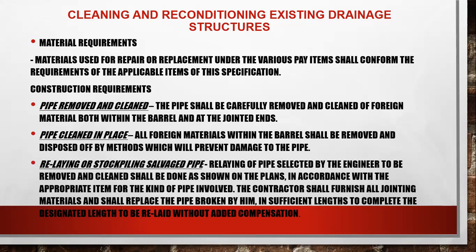Next is relaying of stockpiled salvaged pipe. Relaying of the pipe selected by the engineer to be removed and cleaned shall be done as shown on the plan, in accordance with the appropriate item for the kind of pipe involved. The contractor shall furnish all jointing material and shall replace any pipe broken by him.